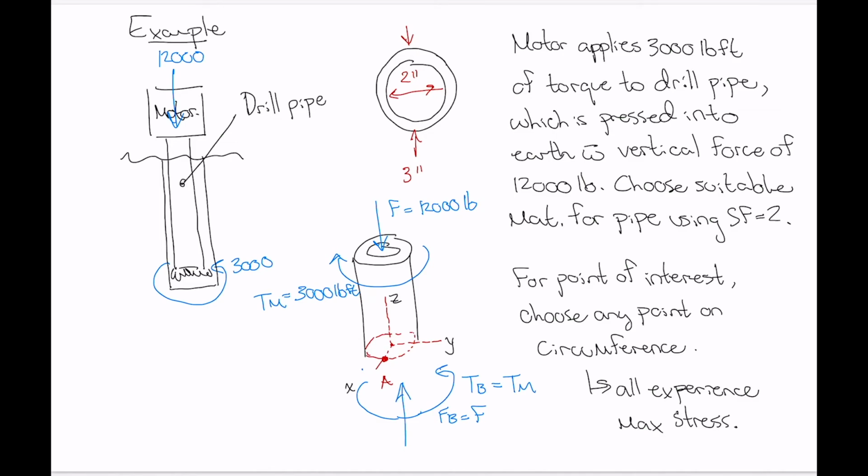Okay, there we go. Now let's draw the volumetric element that's located at point A. It's nice to do this all on the same page, so you've got everything to look at and refer to, at least while you get the directions of the stresses. So this is my element at point A, and let's mark out the bottom plane. That bottom face of the element is the face that's in the section plane of our object. From the internal force, now labeled N, and we'll change this torque to be labeled as we normally would, the torque about the z-axis.